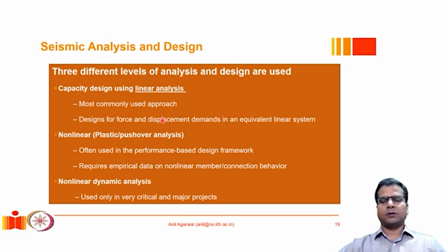There is a design philosophy known as performance-based design, wherein the idea is that the structure should be designed to perform in a certain way under an earthquake of a certain magnitude. That kind of objective cannot be fulfilled with this approach. The approach that can be utilized to fulfill the objective of performance-based design would require some level of nonlinear analysis. The commonly used method in performance-based design is known as the nonlinear pushover type of analysis.